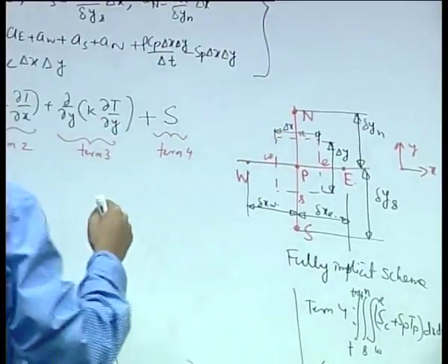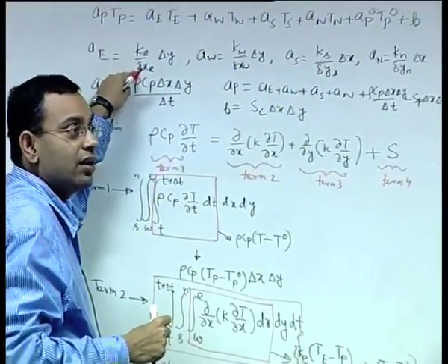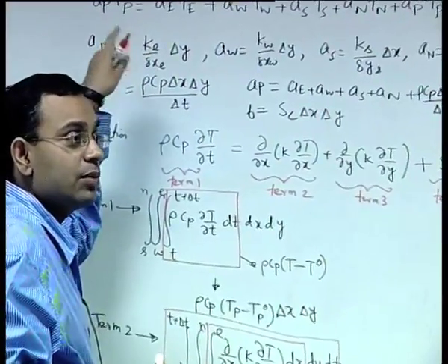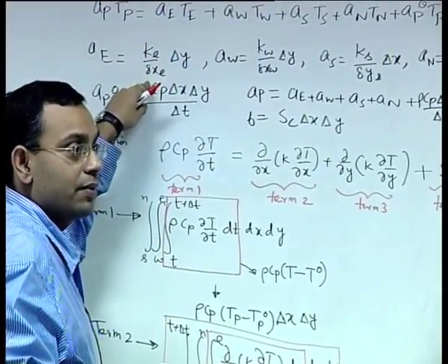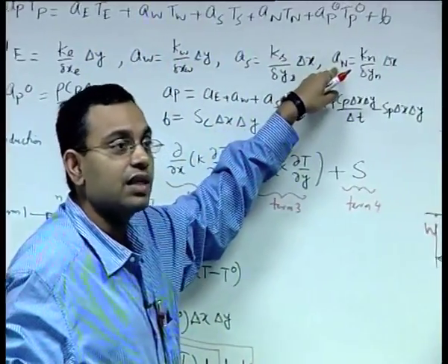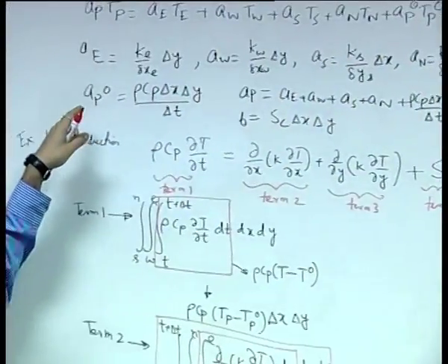So, it is just like conductivity into area of the face by length, Ka by L. What is that? Conductance. Inverse of that is resistance, thermal resistance due to conduction, L by Ka. This is Ka by L. So, these coefficients physically represent thermal conductances of various phases.